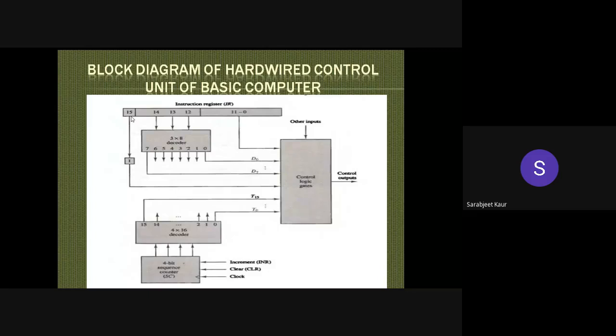If it was direct or immediate, whatever mode is there, then accordingly the address is being supplied from here, right? This mode bit is further transferred into a 1-bit memory element called a flip-flop, which is supplied to the control unit as well, so that it can infer the meaning of this mode bit and accordingly decide what operation is to be performed. Is this clear? This upper half of this block diagram is clear to everybody?